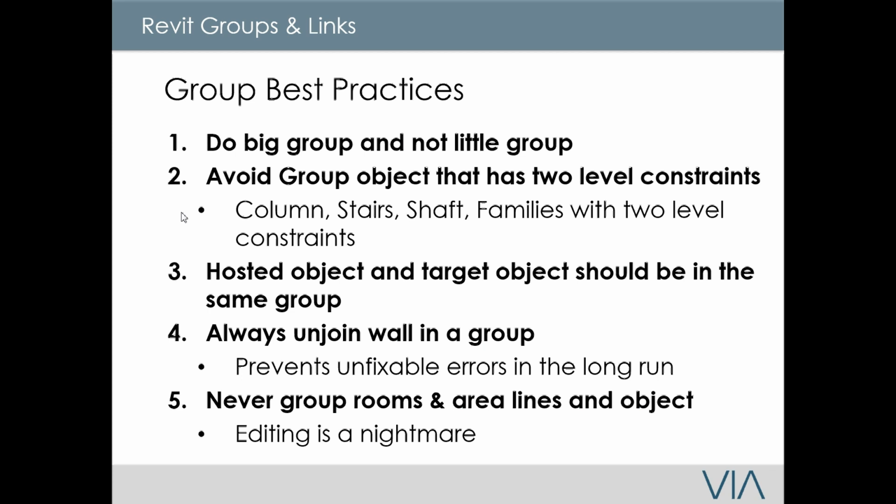If you're using 2014 or 2017 or lower, you cannot schedule a kitchen or bathroom layout. So if, let's say, the client has different types of unit layouts for kitchens and bathrooms, you cannot do that in the older version. In a newer version, if you're using 18 and 19, then you can do it. But I still don't recommend doing little groups. I would prefer you just do the massive one, so it keeps things very, very organized.